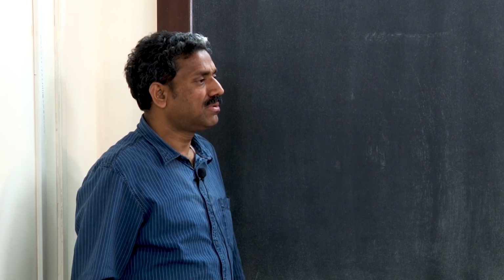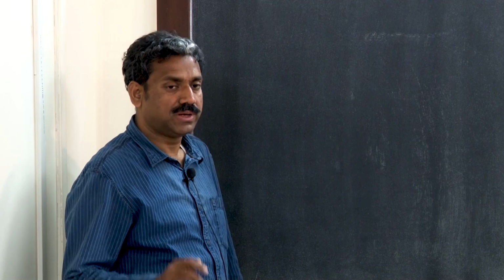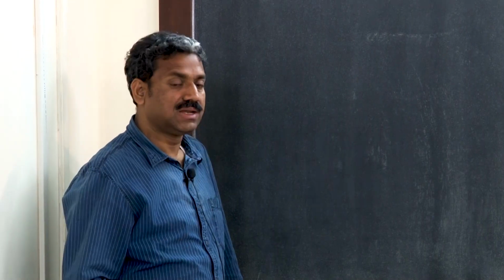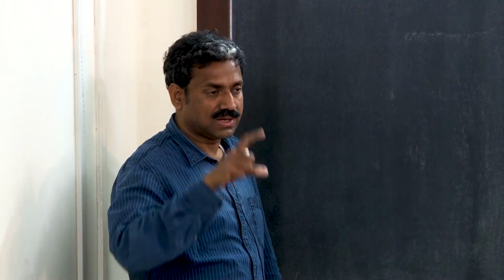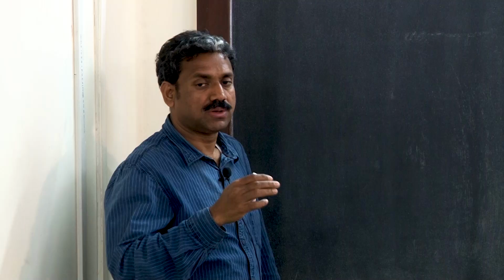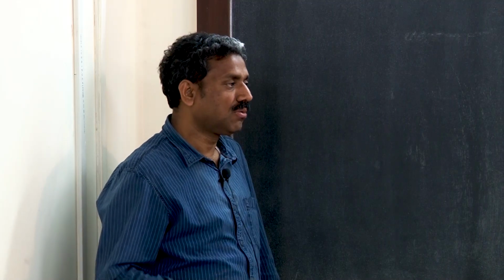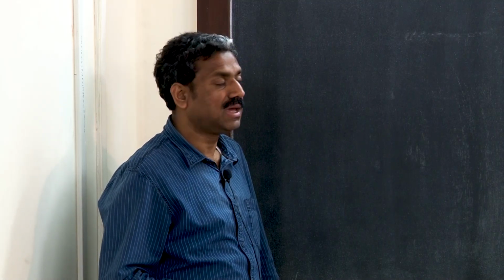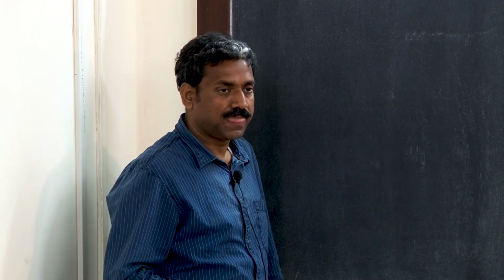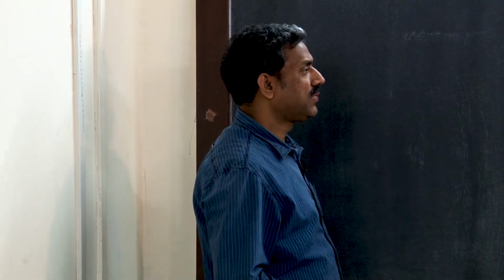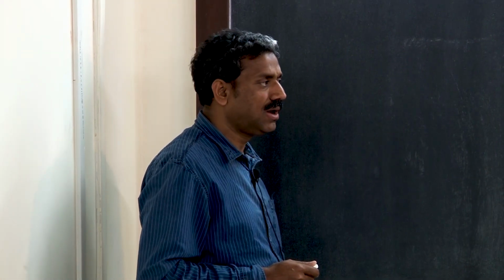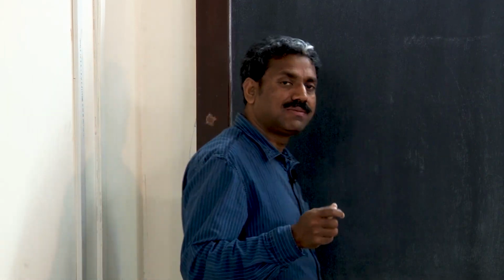We have also expressed the lateral deflection as well as the axial translation using the quantity lambda, that is root P by EI, and also the elliptical integral of the second kind. Anyway, now what we are going to start is once again a discussion on buckling of column, but we are addressing a little advanced topic.